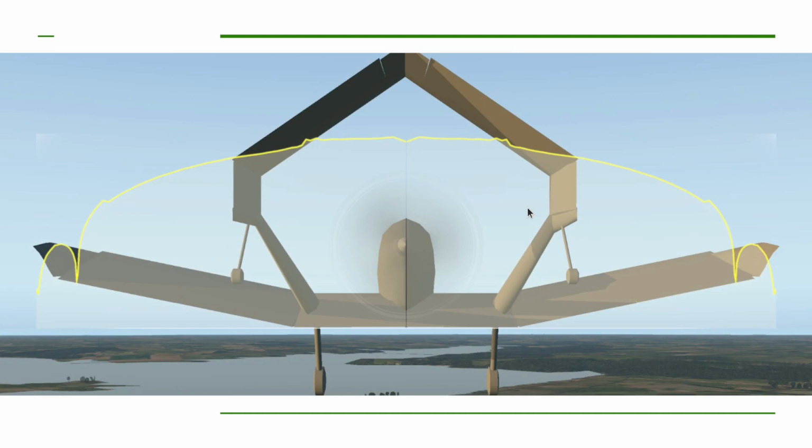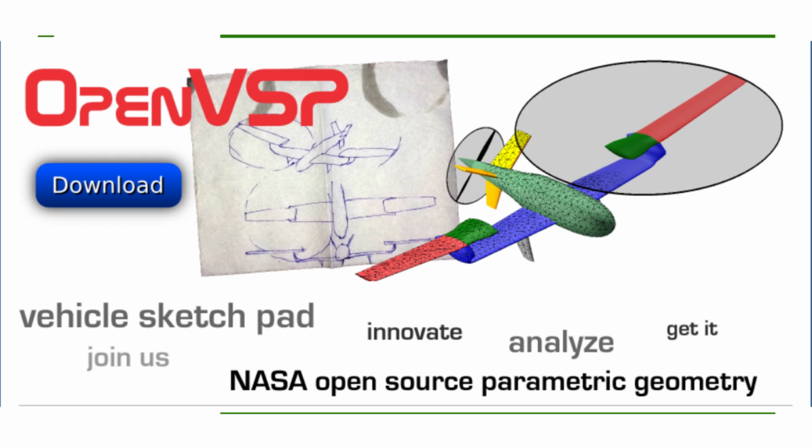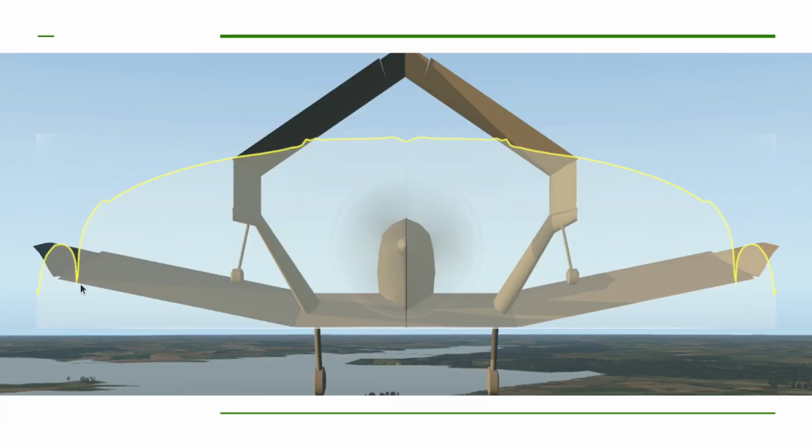Now, in the introduction, I was a little bit brief on what a load distribution is. I've got a picture here of the UWS-4 that I did when I was flying it in the X-Plane 11 program, and we're looking at the rear of it. I've calculated a load distribution for this plane using OpenVSP, and I've superimposed it on the airplane here. That load distribution in the spanwise direction, so from one tip to another, is this yellow line that you can see here. This particular distribution is at a pretty high angle of attack, something like 18 degrees, but you can kind of get an idea of what we're talking about. The height of the line right along here is how strong that lift is in that particular spot along the span.